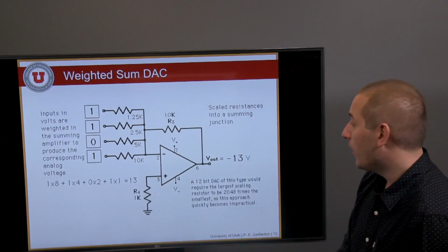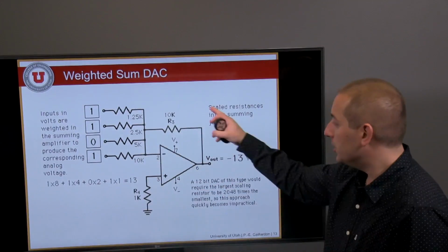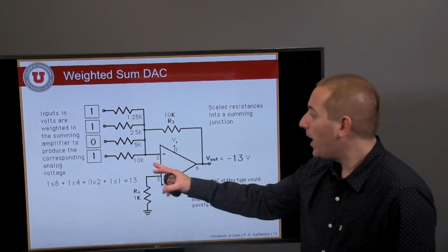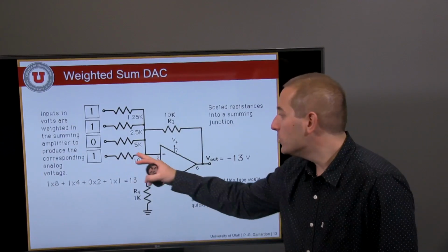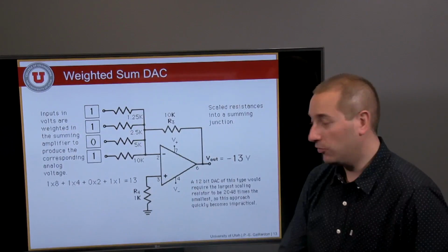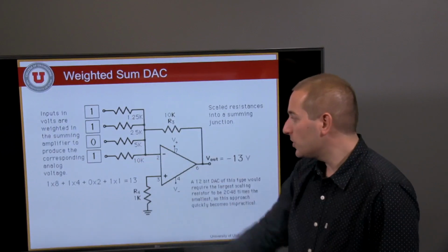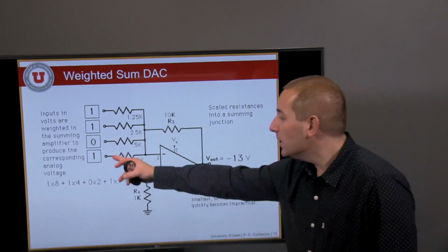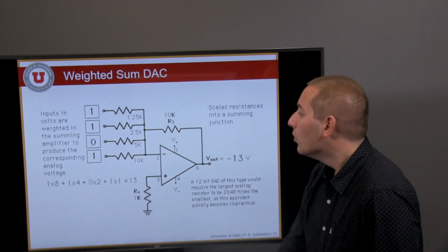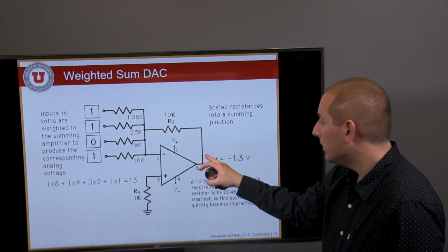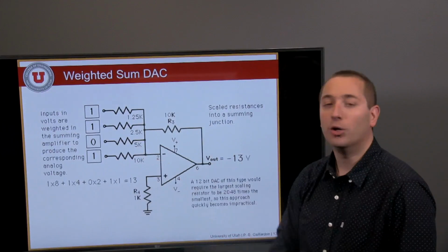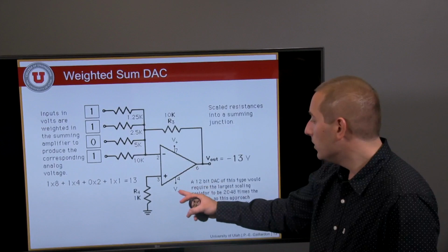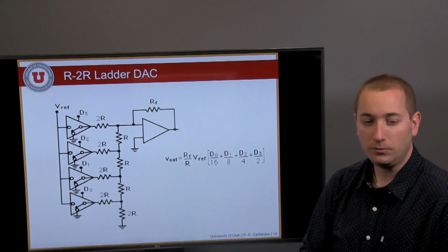Here is a summing amplifier. So you'll have an op-amp right here, with the output that you get here depending on the values that you find across those input resistors. Those input resistors are implemented as powers of 2, and the input code right here will basically inject more current into the system that will in turn generate an output value in between V minus and V plus.